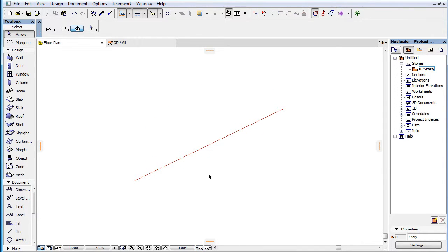When a straight linear segment or element edge is explicitly marked as a snap reference, the two endpoints of the edge are implicitly considered marked as snap references. This way, you can easily find the main axis directions from either of its endpoints and the perpendicular direction to the marked edge from either of its endpoints.